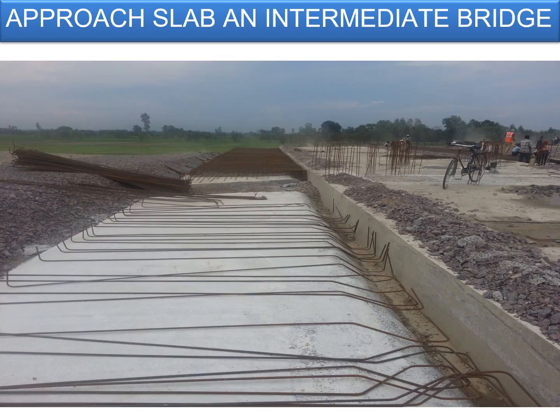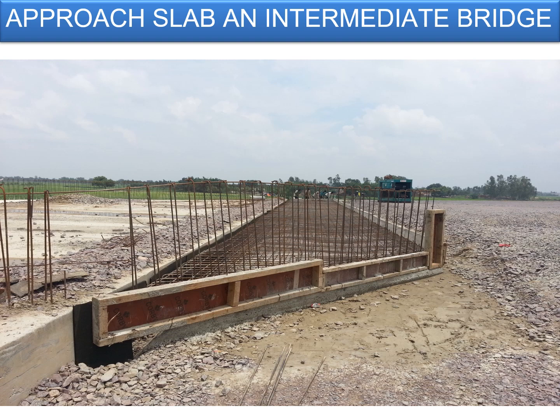Then to construct the approach slab, you need to have a PCC on the gap between the bridge face, the back of the abutment wall or the back wall, and the existing road. And then this will be covered with an RCC slab of say 300 millimeters thick, and maybe around 3 meters or 3.5 meters in length along the line of cross section of the road pavement. So this is the slab which is generally known as the approach slab, which is acting as an intermediate bridge or covering the span between the existing structure and the roadway which is meeting or approaching the structure for completing the project.